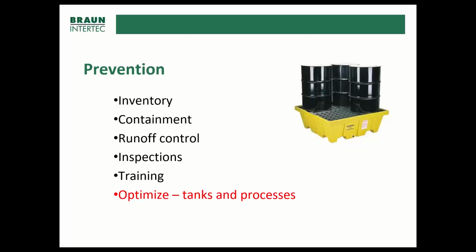For most oil storage, either in tanks or in portable containers or in drums, you're required to provide secondary containment equal to the volume of the single largest container in that containment area. So you could have a mixture of 55-gallon drums and perhaps a couple of 500-gallon totes. The amount of containment that you need in that area is equal to the largest size, so that 500-gallon tote. Now, if you're outdoors, you also have to include some accommodations of extra volume for precipitation.